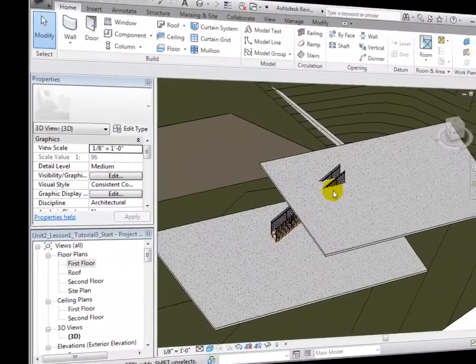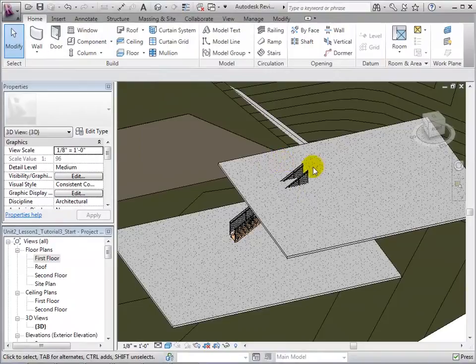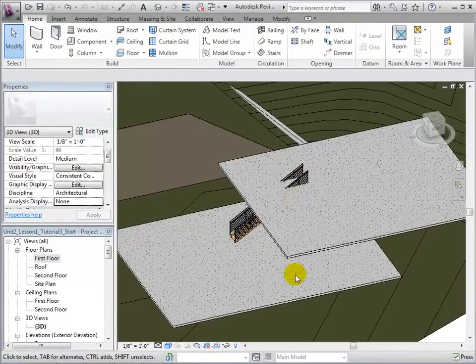Sometimes, stairs are placed in the middle of floors, and therefore, openings must be provided for access. Before cutting an opening, we must determine how much of the floor we need to remove. To do this, let us select the stair and take a look at its properties.